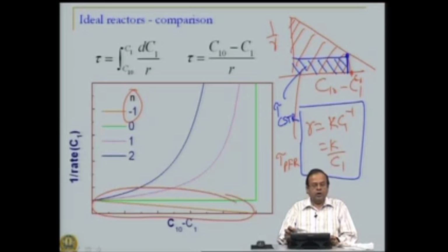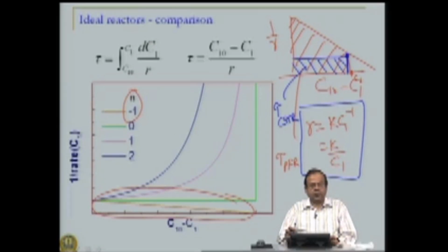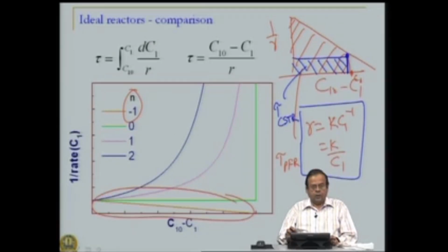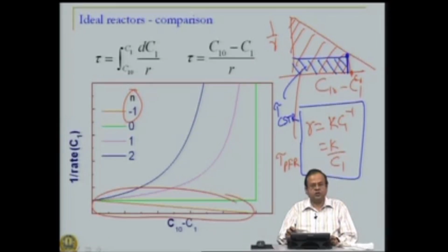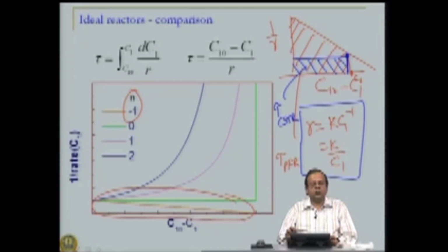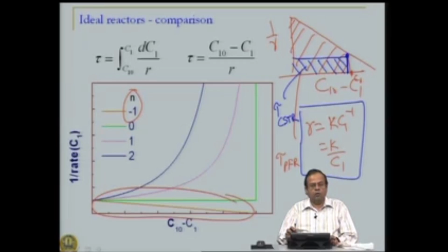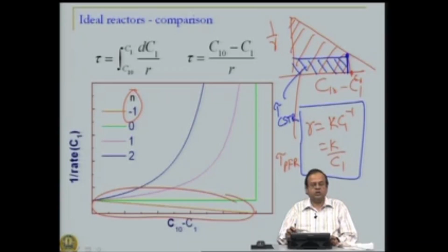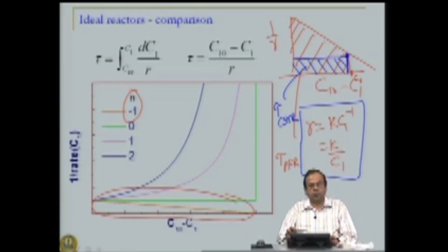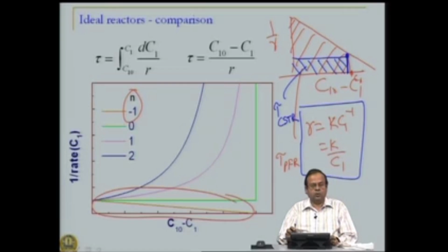Again, qualitatively we can explain it as follows. Stirred tank reactor, because of its assumption of a well mixed reactor, the concentrations drop down to a lower value instantaneously, whereas the concentration decrease from the inlet to the exit in a plug flow reactor is more gradual.